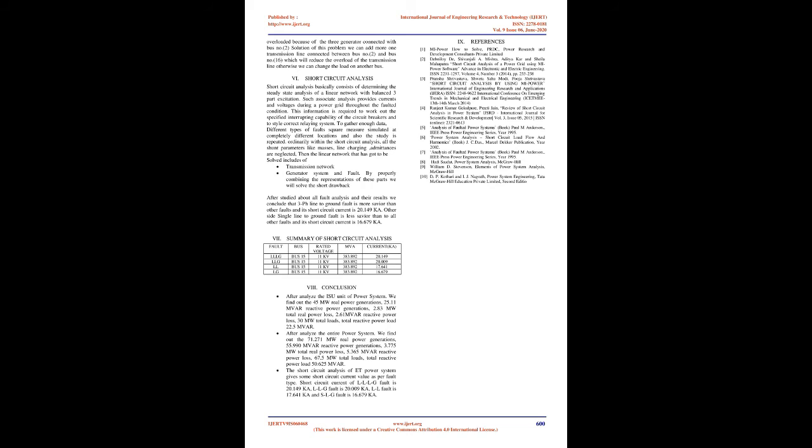The principal information obtained from power flow analysis, also known as the load flow study, is the magnitude and phase angle of the voltage at each bus and the real and reactive power flowing in every line. 4. Load flow diagram of entire system. 5. Load flow result of entire system.